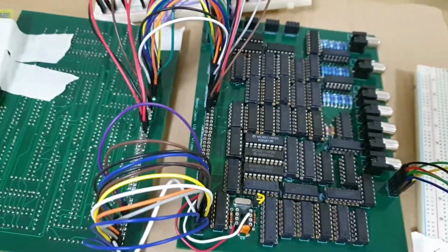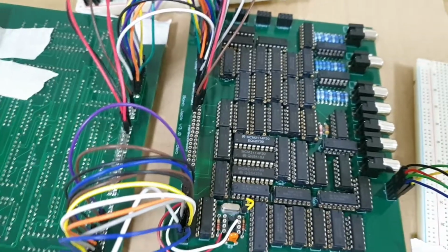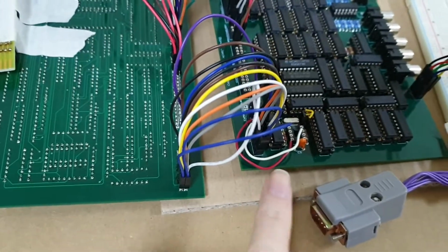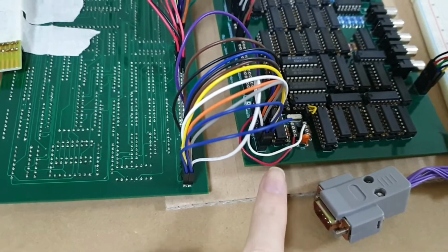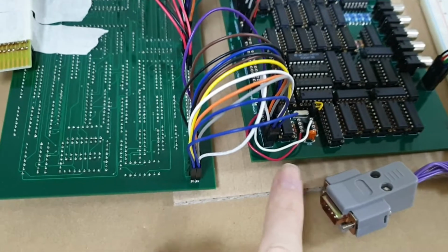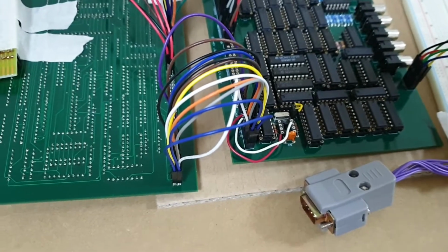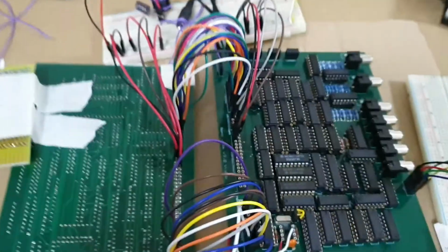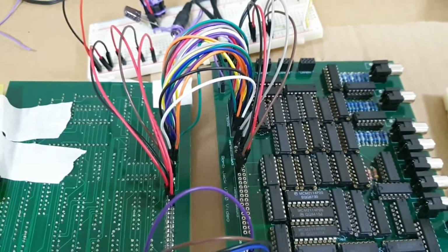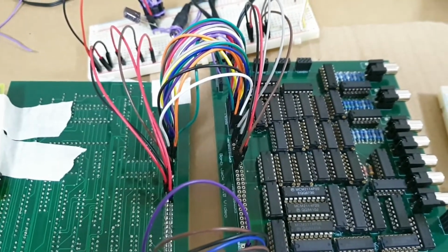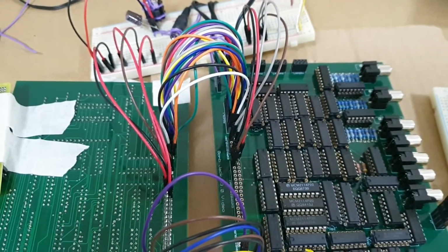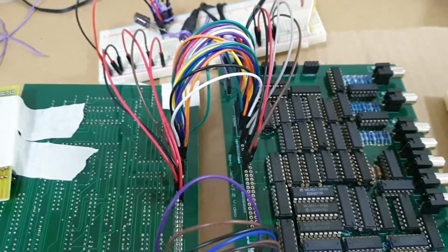Also, for these signals here, as appropriate, I've tied underscore display enable to be low and display enable to definitely be high. Okay, so none of these are going to be floating anymore. We're not going to be introducing any spurious lows when they should be definitely hard highs. So it seems to be a lot more stable now.